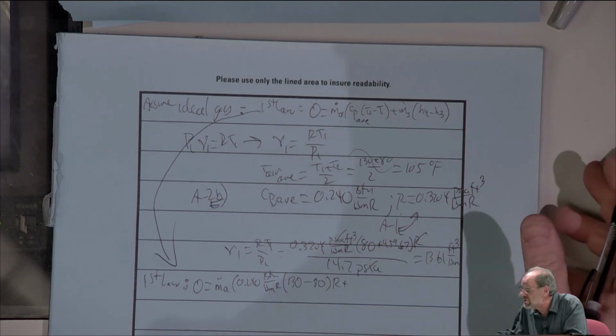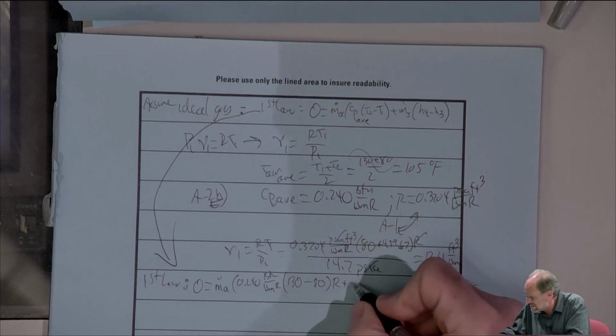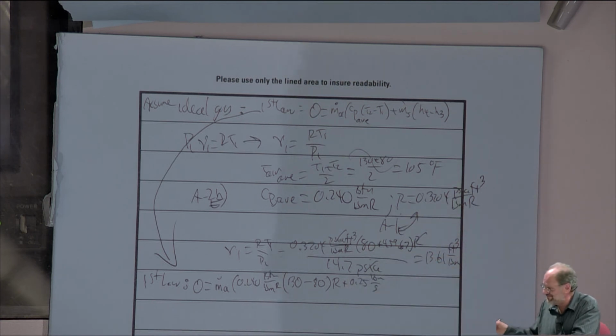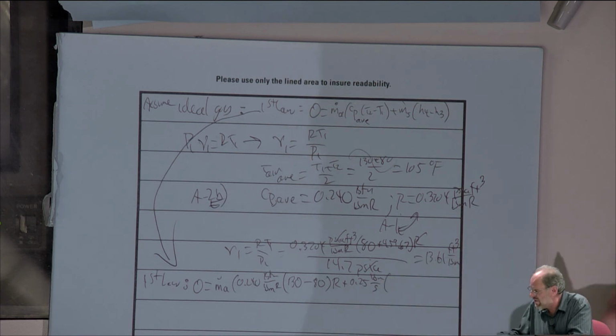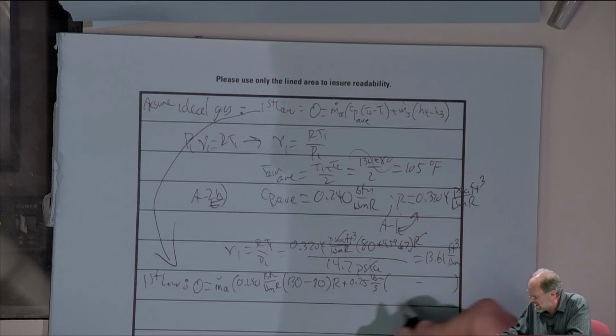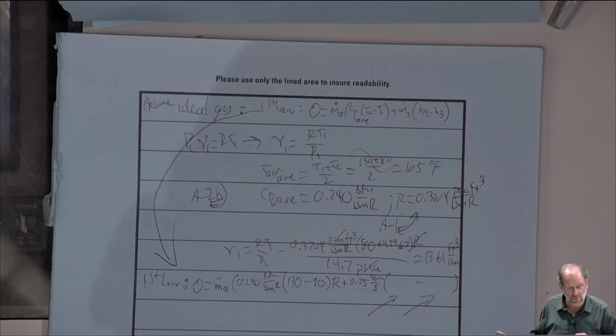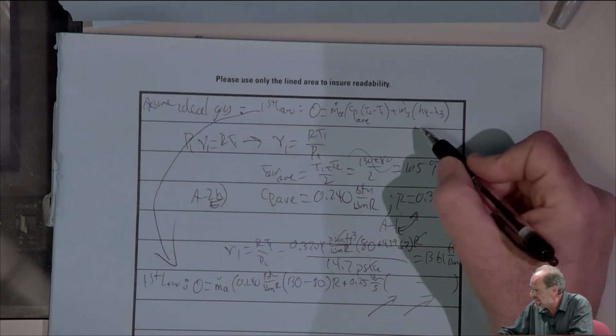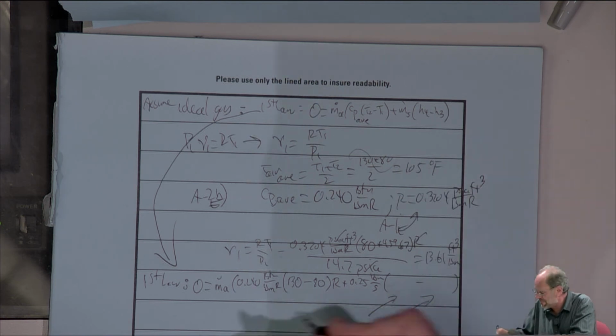The steam mass flow rate has been given to us, so 0.25 pounds mass per second. And we have to look up some enthalpy data, which I did not quite do yet. So this data is going to have to come from our tables. We know that at least at state point 3 it's steam, but what about state point 4?